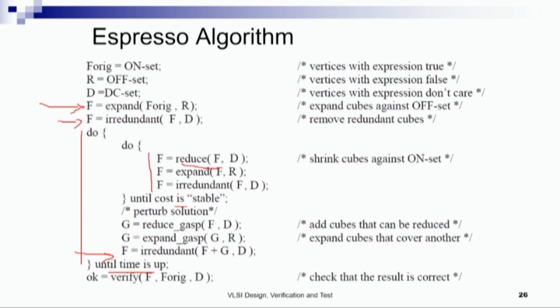A new solution can be obtained by perturbation of an old solution. We can repeat the above process while maintaining the best solution we obtained. So at any point in time, we always keep the best solution, so that at the end of the whole process, after all the iterations that we have done, we ultimately get the final best covering, and the minimum logic expression.